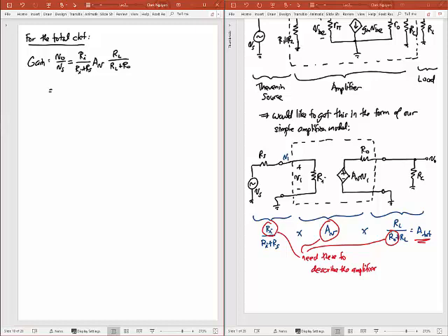So I could say this is then equal to my input resistance I derived as R pi in parallel with R1, parallel with R2. So that's going to be divided by another R pi, parallel R1, parallel R2, but then plus Rs. Okay, the voltage gain A sub V I derived as minus GM times RC. And the output resistance I derived as just RC, so I can write this as RL over RL plus RC down there. But now I can take a look at this, right?